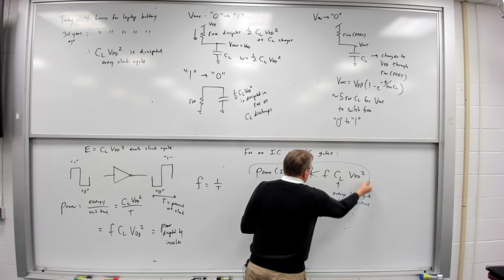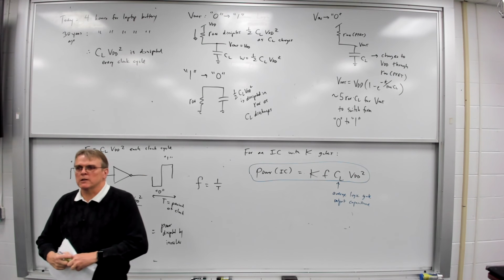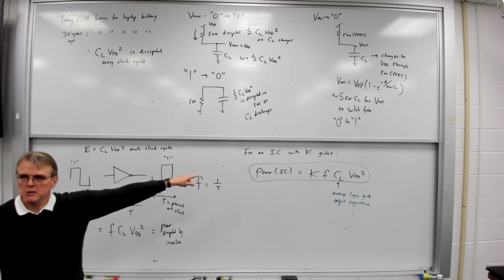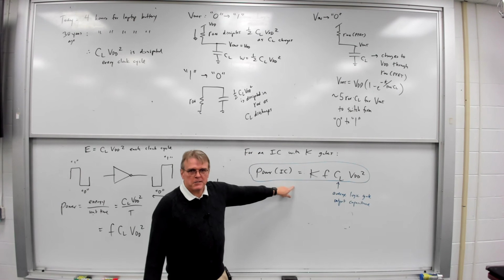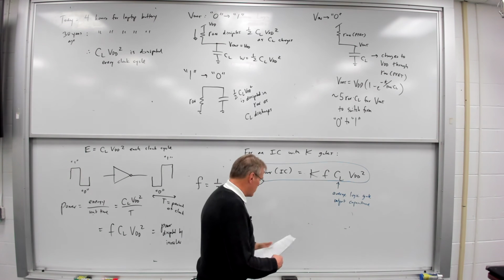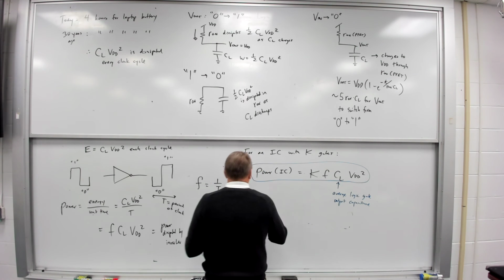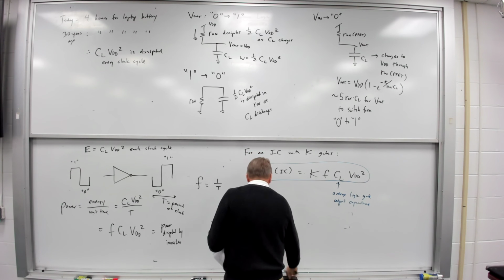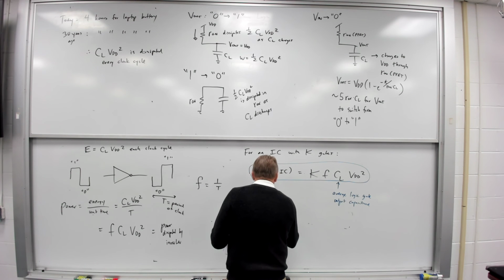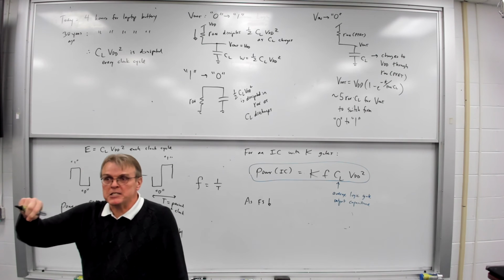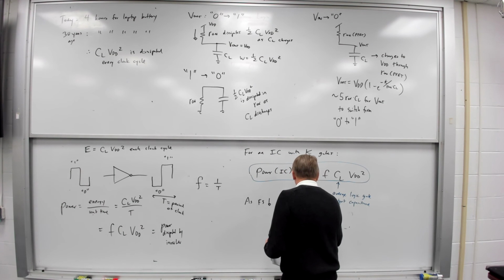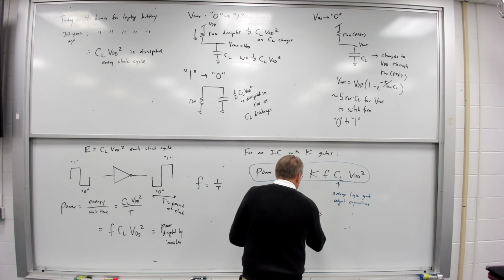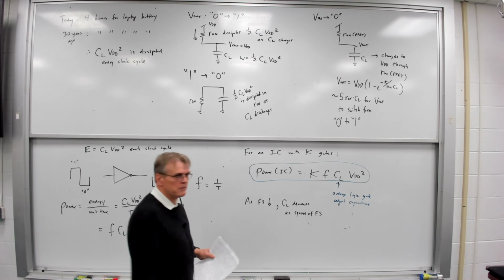Okay, guys, this is the fundamental design equation that every person who designs every computer circuit in the world has to work under. This dictates what you can do, how much power you're going to dissipate, how much power you're going to need. Okay? So, let's think about this. As I shrink the feature size, then the capacitance area goes down as the square of feature size. So that basically shrinks as the square of that feature size.